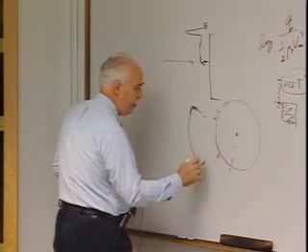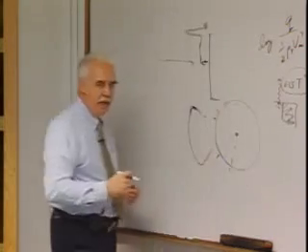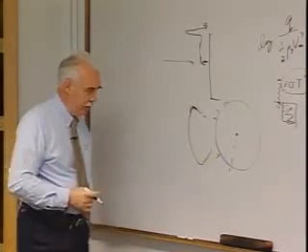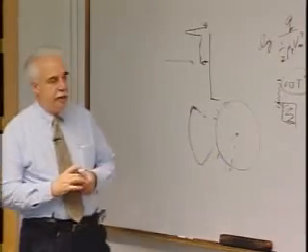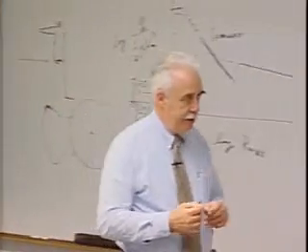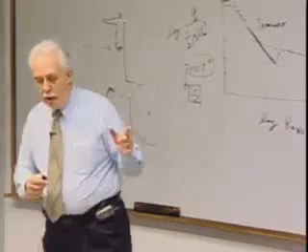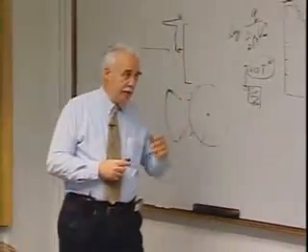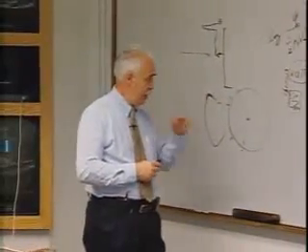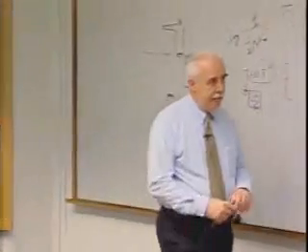This is only from an aerothermodynamic standpoint now, and so I don't have this corner edge heating problem nearly as much as I did. Well, that's fine, except a zero L over D vehicle gets kind of high G's coming in, and you don't have much control. And I'll address a little bit of that, and you've probably already heard about the flight mechanics control. In any event, I need some L over D, so I go to angle of attack.